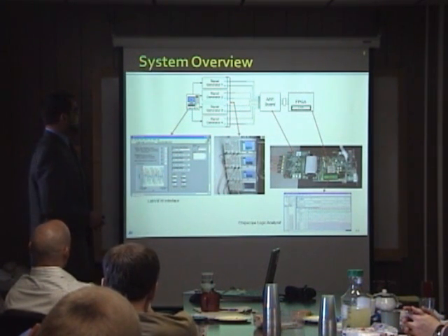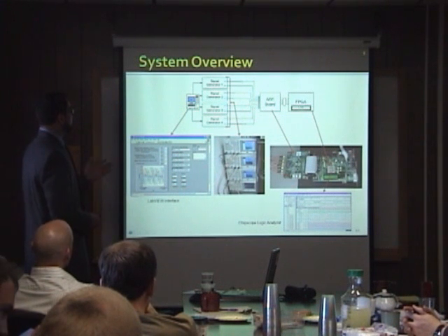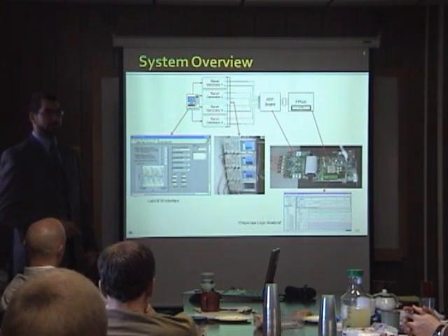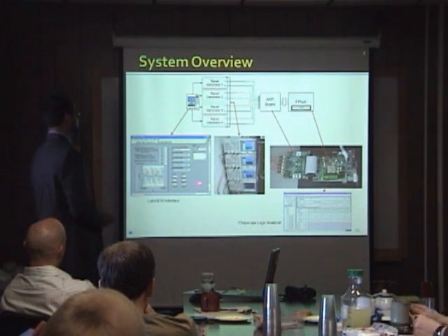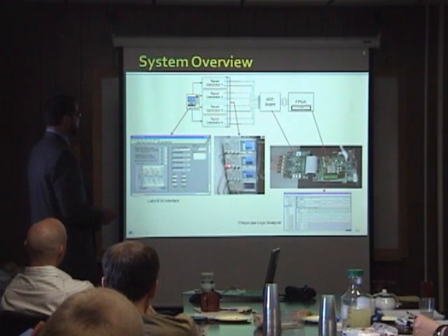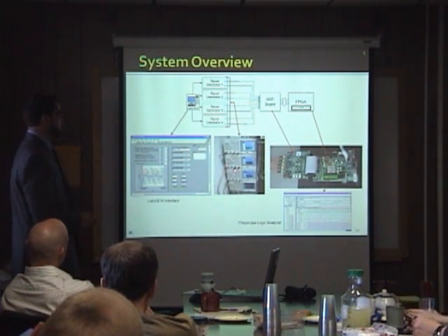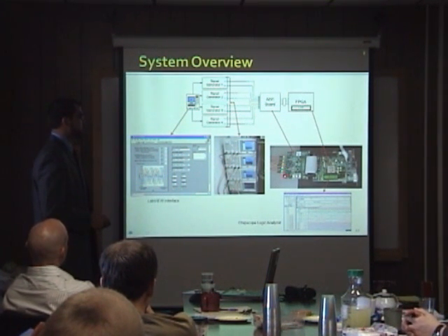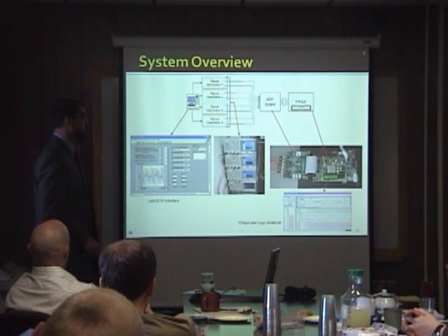As they ping on the array and go all the way to the translation board, then are down-converted and sent to the DAC card. So that's what the LabVIEW and the signal generators are for. And then this one sends the signals to the ADC board through SMA connections.